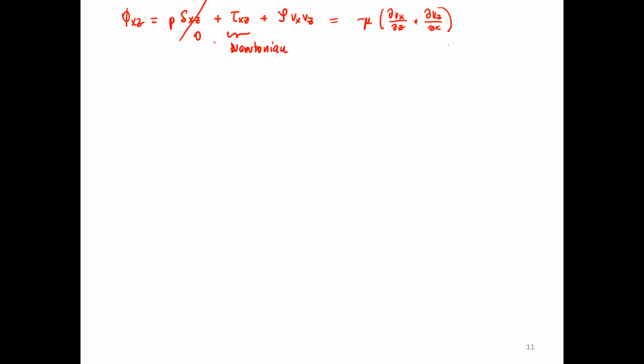Yes, so I have that additional part that depends on the divergence of V, and we are assuming an incompressible fluid. For incompressible fluid with constant density, the divergence of V is 0. We're going to get to proving that, but for now, just take it as a definition. So divergence of V is equal to 0 for incompressible fluid with constant rho.